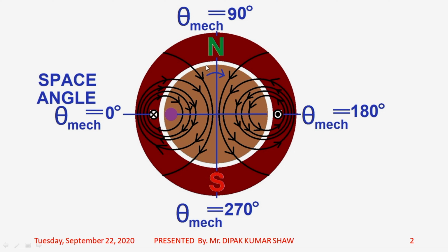Now yes, we need to take care. What we need to take care of, when we are deciding upon what should be the length of the air gap between the stator core and rotor core, is that we should actually try our best to keep the air gap between the stator core and rotor core as small as mechanically it is permissible. So what is our focus?